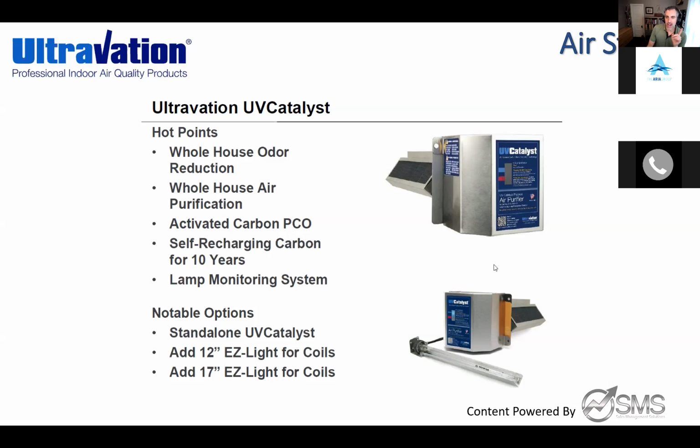Yeah. I will say though, from a training perspective, you should never just go right. Everybody's all concerned about airborne viruses, right? And it's like, well, listen, you can't skip the coil. It's a big no-no, because great, I'm treating the air supply, but if I've got a possible petri dish going on in my system, I'm just adding to the problem. So that's why I always try and push people: okay, I know everybody's all about air supply right now, but don't forget about your equipment, because you still have particulates passing by the filter, no matter how good the filter is, and you have moisture on the coil. So protect the coil.